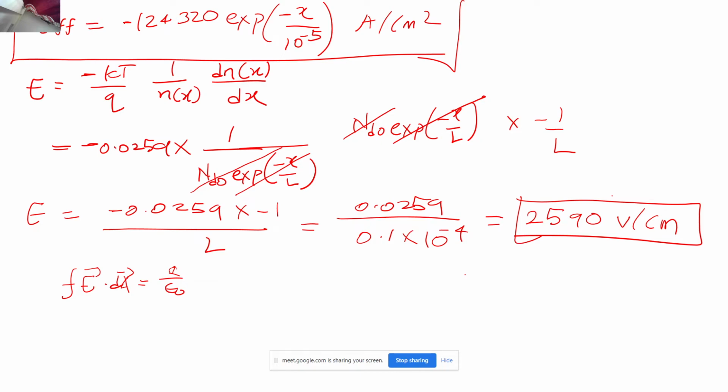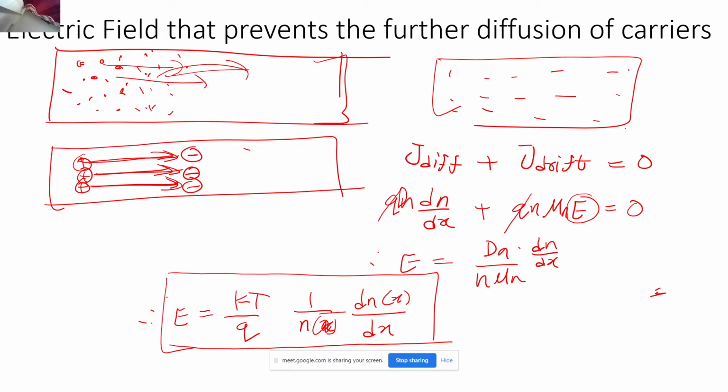You see that? So in this case also, in the diagram that he has shown, go back to the diagram, the charges you showed. When these electrons move away, electrons are the free charges. They can go wherever they want, right? And because you have an excess of electrons, they diffuse across the semiconductor. And what is left behind? The positive charge. That's the space charge we say, right? Because you are essentially introducing what type of dopants? It's an N-type semiconductor. What type of dopants? Can anybody say?